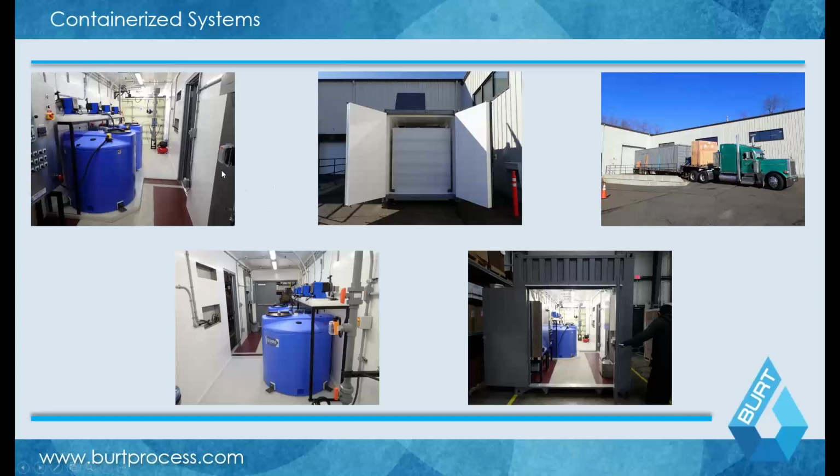And you want to have access in certain areas. So like here, you have predominantly access around your reagent tanks, your control systems, and then back here where you have your instrumentation for calibration. A lot of the sidewall, where the tank would typically be up against the wall, is really within the actual body of the container. You also have certain things in the container itself. You have a lot of lining, different sensors for leaks, environmental controls, acid-resistant lining, as well as chemical safety showers and drains and sumps installed in these types of systems.